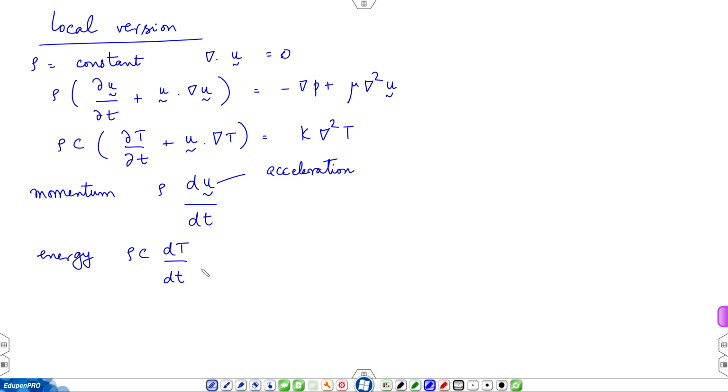So, this term, like acceleration, it is the temperature content, which is internal energy being carried by rho c times temperature, well, actually I plus p over rho, as we had discussed, which is internal energy plus p over rho, which is enthalpy being carried by the flow. So, it is thermal signature being carried by the flow, like acceleration. There is an analogy between the two, except that acceleration is a non-linear term, this is a linear term.